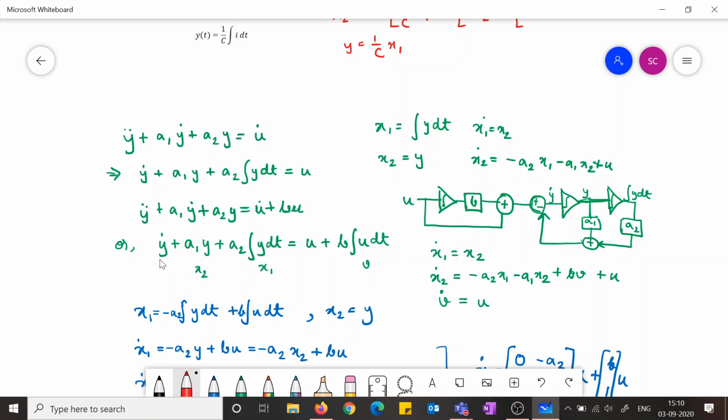And now I applied that idea. So in the block diagram idea, when we are deriving state equations from block diagrams, you might have noted that we are taking the output of the integrators as states, correct? So the output of the integrators are considered as the states. So by utilizing that idea, I also defined this integration u dt as a new variable.